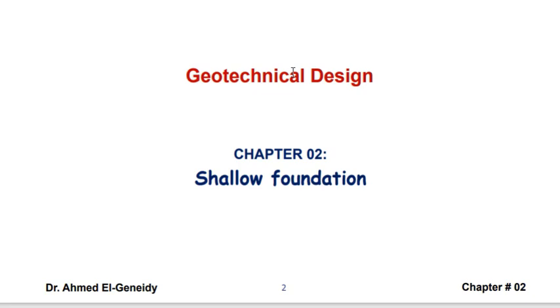But really we cannot put the foundation on top of the ground for two reasons. The first reason is the surface part of the ground is usually disturbed, so I cannot just put my foundation on a disturbed soil. Second thing is that it will be affected by the environment, rain, hot and cold weather, sand, so it will be affected.